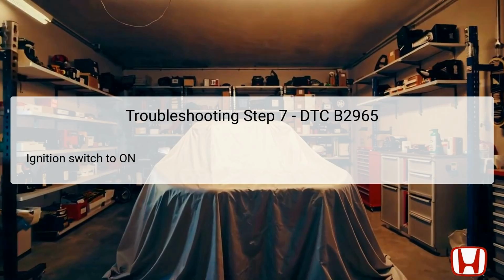After disconnecting the rear AC control unit connector B, the technician must turn the ignition switch back to the on position. This action is necessary to supply electrical power while conducting tests on the disconnected connector. By turning on the ignition, it allows for checking the voltage at the connector terminals without having the rear AC control unit powered up. This distinct testing procedure helps ascertain whether the problem lies within the unit or the wiring. The HDS interface may still be used in conjunction with this step for supplementary information regarding electrical functionality.